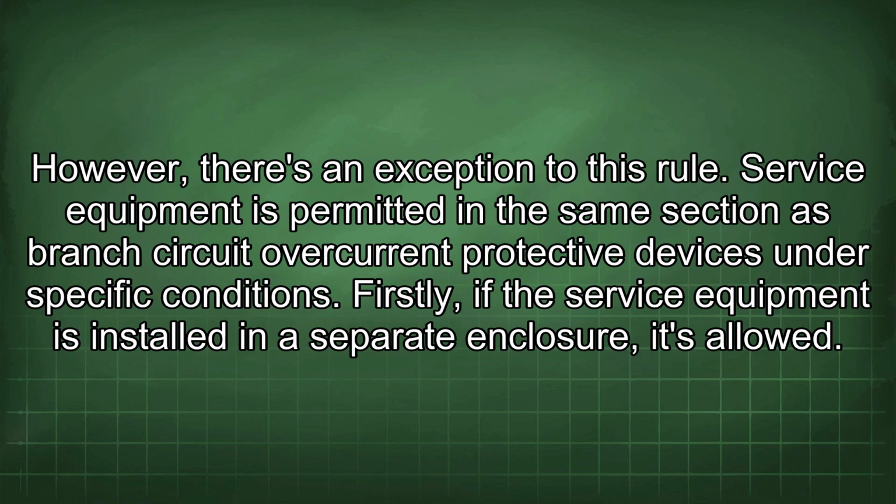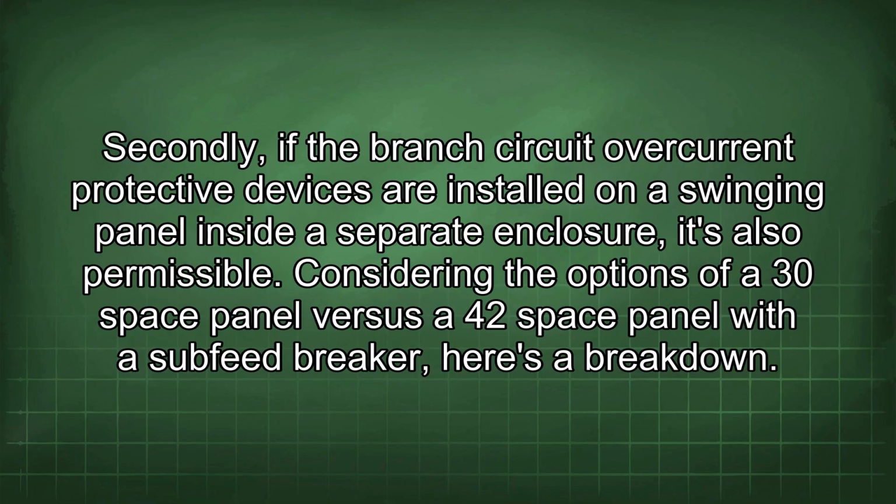However, there's an exception to this rule. Service equipment is permitted in the same section as branch circuit overcurrent protective devices under specific conditions. Firstly, if the service equipment is installed in a separate enclosure, it's allowed. Secondly, if the branch circuit overcurrent protective devices are installed on a swinging panel inside a separate enclosure, it's also